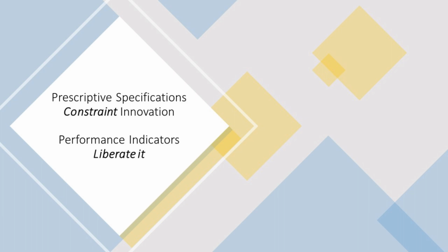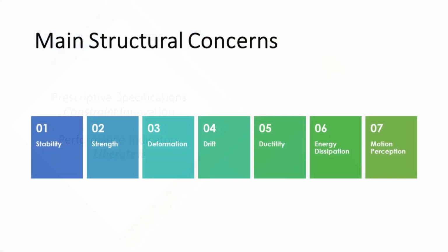So it leads to innovation. The contractor can innovate, they can add more material, develop new ways of making it. They don't have to follow how much slump the concrete has. They just have to make sure that the final product will be what is expected. So that's another main difference between prescription and performance, that performance basically helps people to innovate and not restrict innovation.